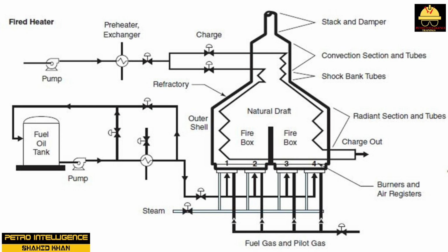A space of 1.5 to 2 feet is considered to be a safe distance between the open flames and the radiant tubes. The burner's flame pattern should be less than 60% the height of the firebox. The radiant section is engineered to distribute the radiant heat evenly. Modern burner design consumes 100% of the fuel with a nominal excess of 10 to 15% oxygen.